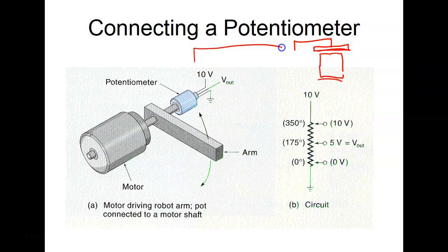Over on the very end, they have a linear pot. As the carriage moves across, pin 2 gives us a voltage that represents the position. It's very simple to do, and then we can bring that into some device where that voltage represents the exact position. We have two of them over there. It wouldn't surprise me if they don't have one somewhere else. We can process it with a programmable controller really easily. And these things are really cheap, a lot cheaper than encoders.